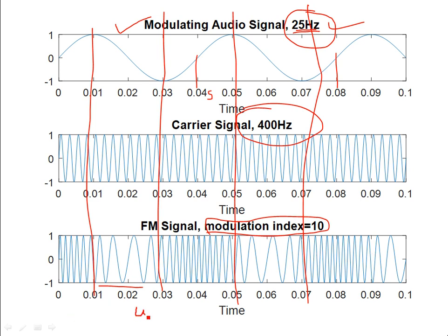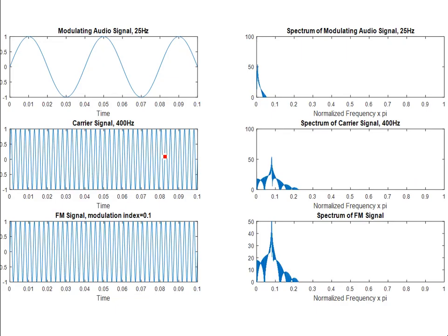Okay, so over here again, let me put it like this: omega c or fc is again the nominal frequency of the carrier as a function of time, and we are varying this with plus the modulation index. Let's call this M, modulation index MI, multiplied by V_a(t). That's how you're varying the frequency, depending on the amplitude and the modulation index of the modulating signal. Now, on the other hand, if the modulation index over here is small, you see that the variation is hardly noticeable. You don't see much bunching of the waves together and relaxing simultaneously.